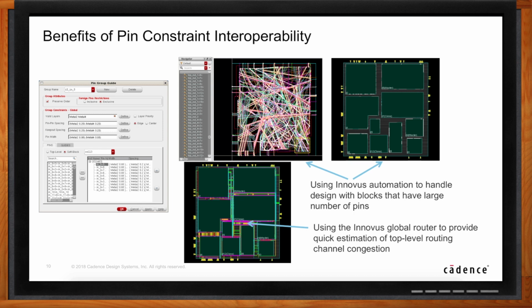Right. So we now have basically a pin placement that looks much neater than the initial design. And we can very quickly then, using the digital technology, run a global route, look at the congestion in the channels, make sure the floor plan looks about right. If the digital engineer wants to change the floor plan, they can do that, and then that's all stored back in open access, and the Virtuoso designer in the full custom world sees any floor plan changes immediately. So it really shows the bi-directional interface between the two worlds. Very cool.